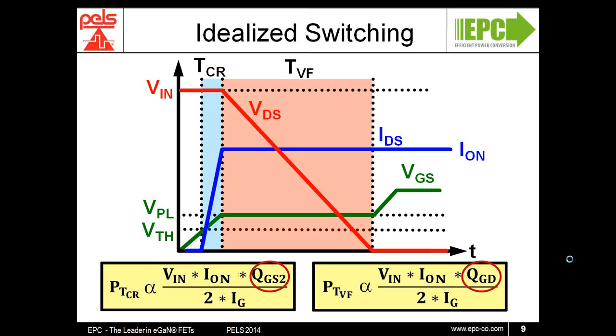If we are to look at a hard switching figure of merit, which basically takes these two terms and adds them together and multiplies this by the RDS(on), you will end up with a near constant term for a given MOSFET or GaN technology, and it can be used to compare the performance in a hard switching application between MOSFETs and other field effect transistor devices. On this graph, we can see the figure of merit on the right-hand side and voltages from 25 to 250 volts.